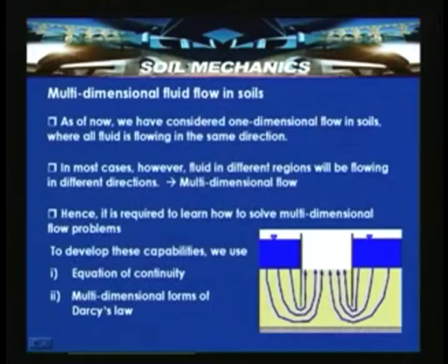To develop these capabilities we use the equation of continuity. This is based on the conservation of mass and the multidimensional forms of Darcy's law. So, again we will be using the multidimensional forms of Darcy's law and the equation of continuity. With the help of these we will arrive at the equation of continuity and its solution, and the application of this leads to calculating the seepage problems involved in earth dams or sheet pile walls.